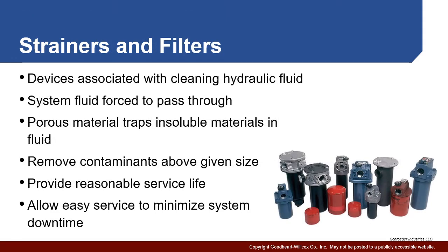So all the various devices that are going to be associated with cleaning our fluid fall in the categories of strainers and filters. If you look here on the right, you can see an example of how they appear. You're actually not seeing the filter itself. This is actually the housing. Fluid would come in this port, oftentimes out the other side, and some or all of the fluid would be put through a filter that is hanging below here. Again, these are usually mounted vertically with the filter itself hanging below, with the idea that the contaminants, usually heavy contamination, tend to drop towards the bottom.